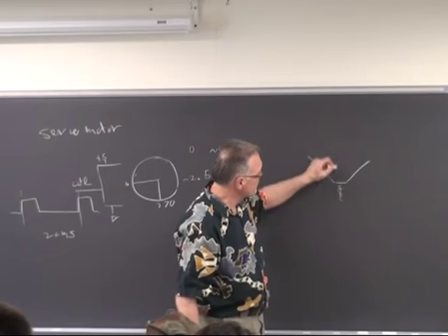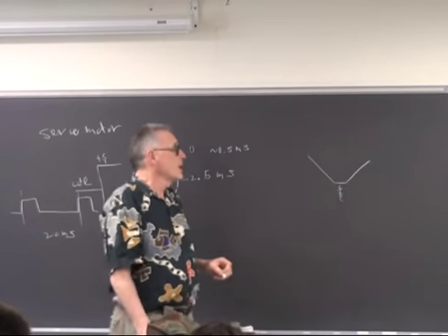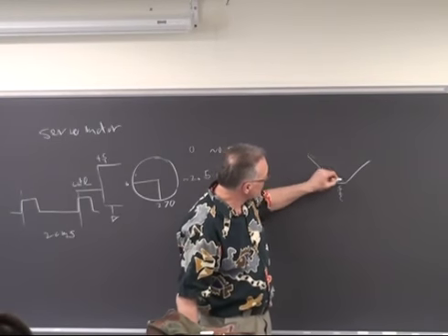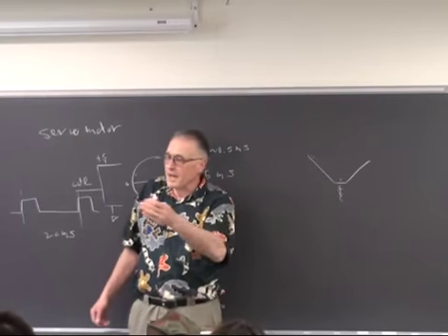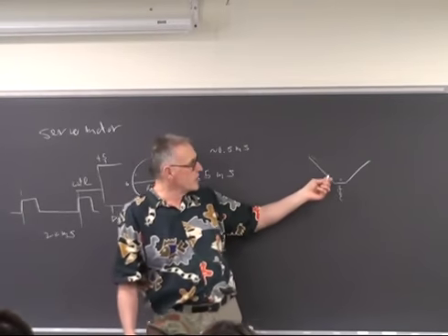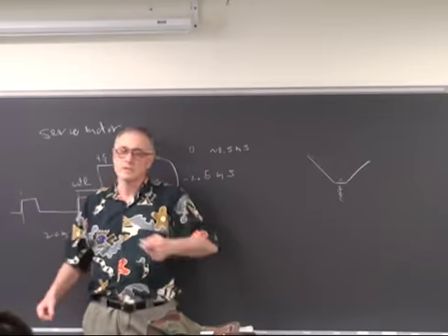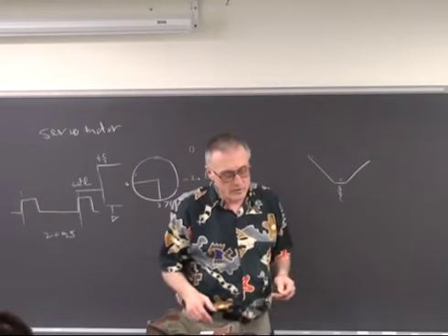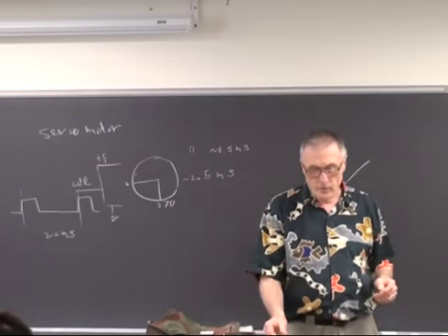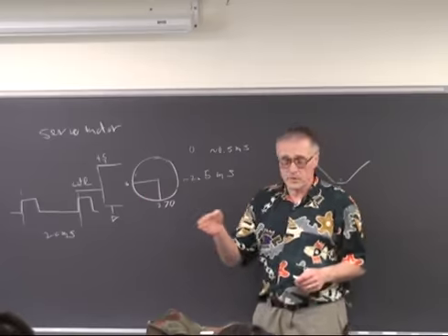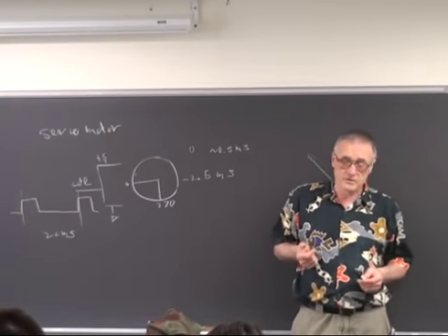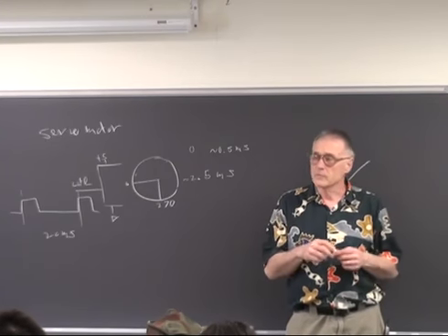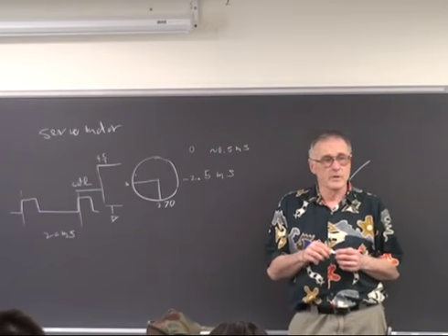Typically there's a coil that's moving some sort of diaphragm back and forth. They're high bandwidth, and so you could, for instance, put a small mirror on one and move a laser beam back and forth very quickly by changing the angle of reflectance at audio rates. So if you need very high bandwidth but not too much motion, speakers are quite useful. There's a version of servo motor which is a linear motor, and there are also versions of stepper motors I'll talk about which are linear motors. What else? Anybody have any experience with piezo motors?